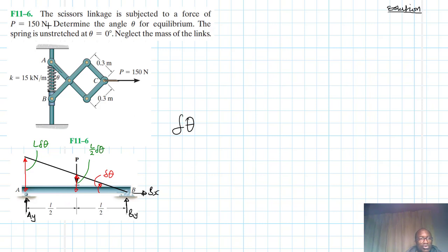Then we know that the total work in a system due to the virtual work, when you've done the algebraic summation, del U is equal to 0. So what we have here, again I said, the displacements have to be parallel to the forces, and these forces can either be applied forces or reaction forces.